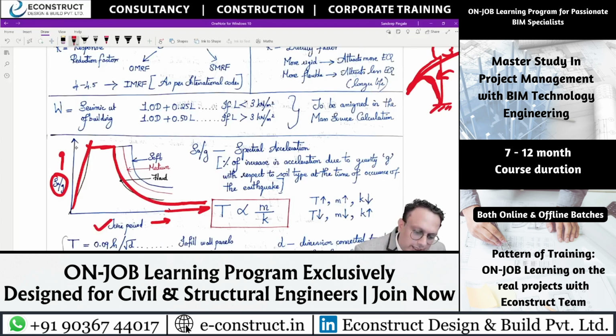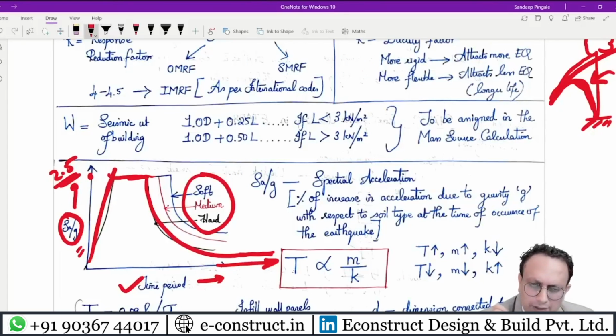In the recent code, if you see the dynamic analysis, in the static analysis it is straight. In the dynamic analysis, it goes like this, the same graph which I am showing you on your screen. It depends upon the soil: soft soil, medium soil, or hard soil. If soft soil is there, then the earthquake force lasts a little longer. If hard soil is there, the maximum value becomes shorter. What is the maximum value at this particular junction? 2.5 times.